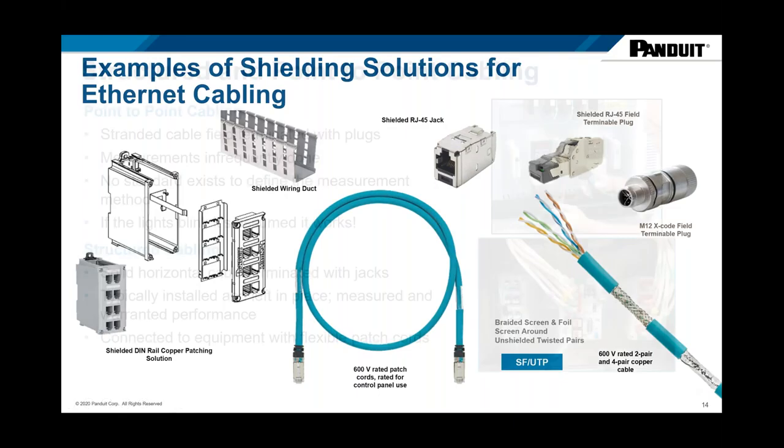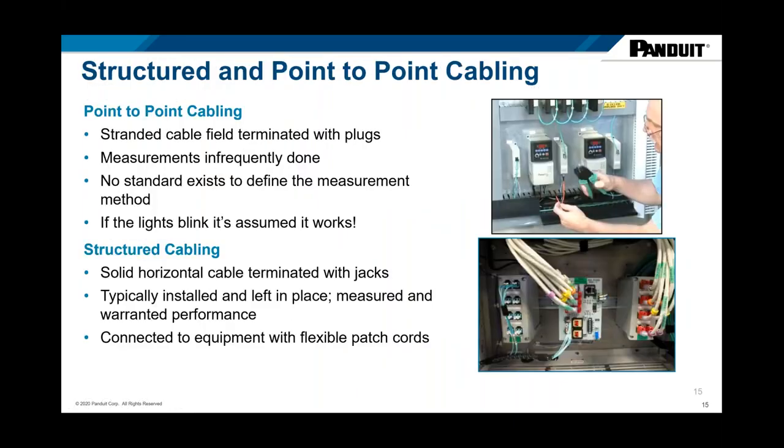All right, so I'm going to come back to the TIA model here real quickly. So both point-to-point installations, cabling installations, and what we call the structured cabling are likely to occur on the plant floor. Using structured cabling in switch-to-switch connections is very appropriate and is recommended by the TIA 1005A, and is actually becoming more common on the plant floors. And we'll talk about why in a minute.